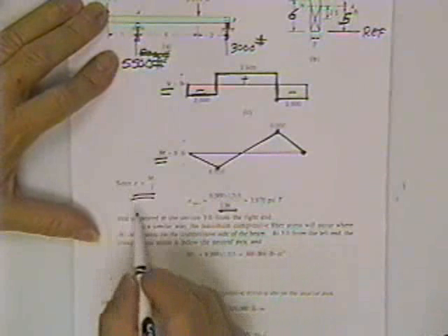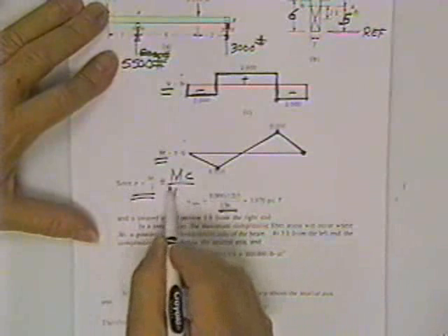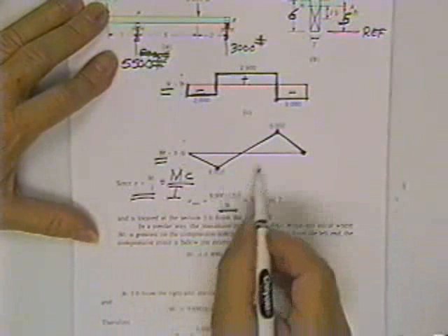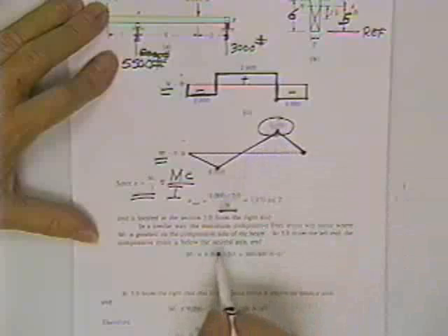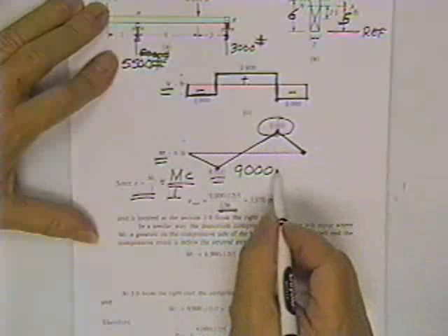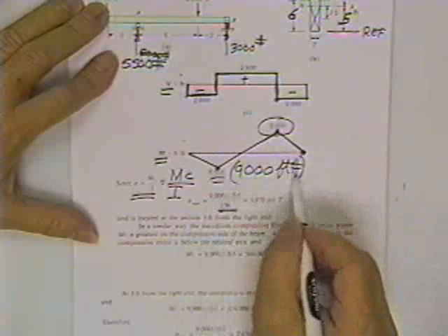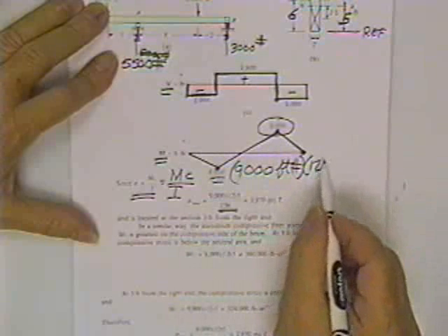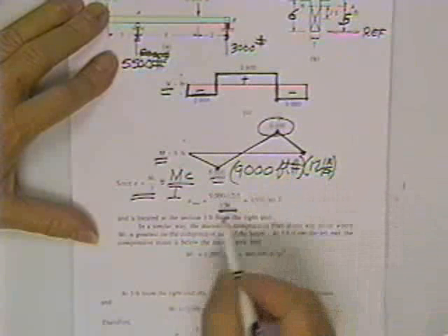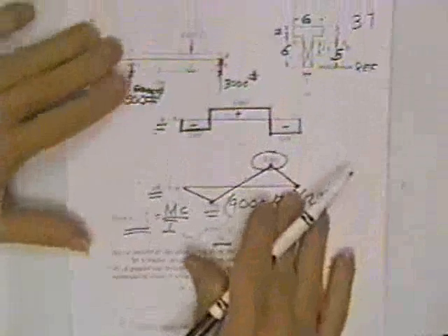The equation for bending stress is Mc over I. In our case, the maximum bending moment was 9,000. In that case, it was foot-pounds. We got our moments of inertia in inches, so let's multiply that times 12 inches in a foot times c. Well, there's 2 c distances.